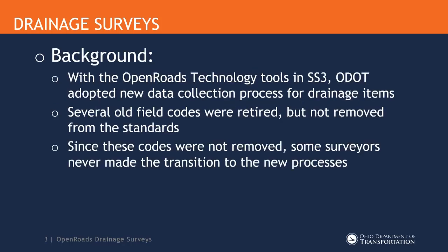So just a little background information. Back in SS3 in the Open Roads Technology Tools, ODOT implemented some new data collection processes for the drainage items. That came from input from some different surveying consultants. It was adopting a process that would allow drawing the drainage pipes using a CSV file with the information for the pipe, connecting from point to point with the elevations and all that stuff.